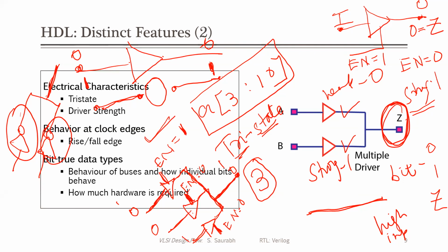You are correct in the sense that suppose this was zero and this one was one, then the output will become one here and zero there, and you will have the short circuit. But why will this short circuit happen? Where is the short circuit path? Short circuit means that VDD and ground get connected through a low resistance path. Where is that low resistance path?